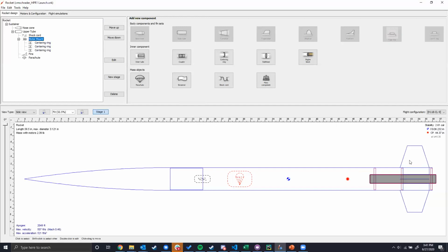As you can see, the fins here also slot into the fin can, hence the name fin can. And you'll typically also epoxy them in place. The other thing, to actually keep them firmly attached, is that you'll typically do what's called a through-wall fin.